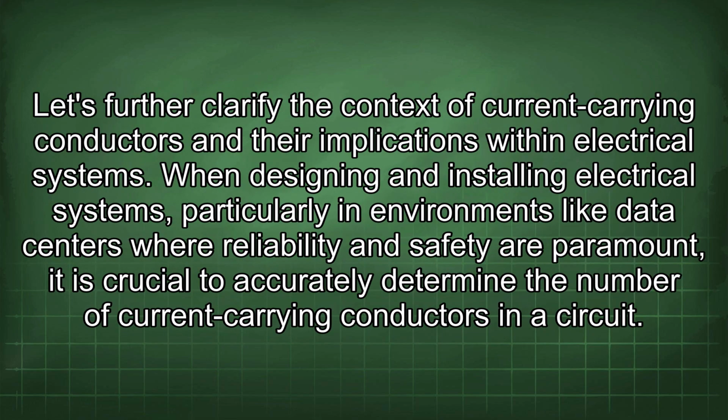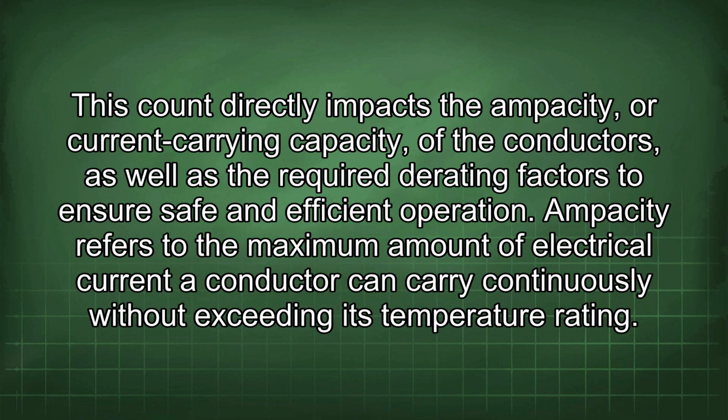Let's further clarify the context of current carrying conductors and their implications within electrical systems. When designing and installing electrical systems, particularly in environments like data centers where reliability and safety are paramount, it is crucial to accurately determine the number of current carrying conductors in a circuit. This count directly impacts the ampacity, or current carrying capacity, of the conductors, as well as the required derating factors to ensure safe and efficient operation.